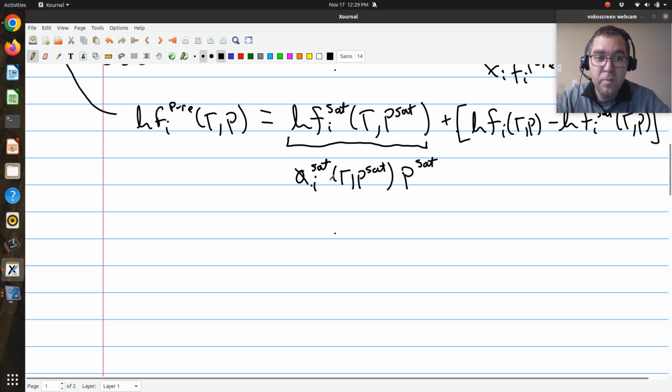And the reason we do this expansion is, if I find that I'm at low pressures, then it might be reasonable to assume that my fugacity coefficient is just equal to 1, so that my fugacity at saturation is just equal to PSAT. Okay, so it gives us this hierarchy with which we can make approximations.